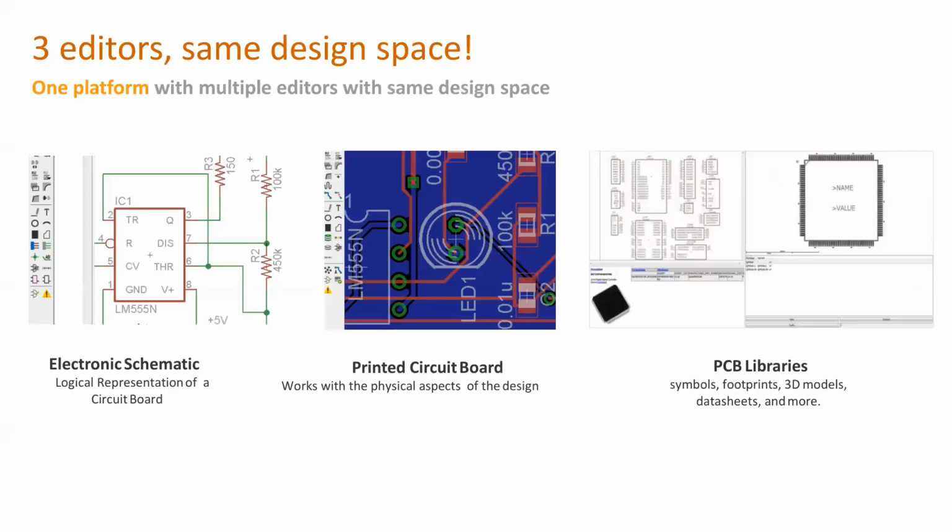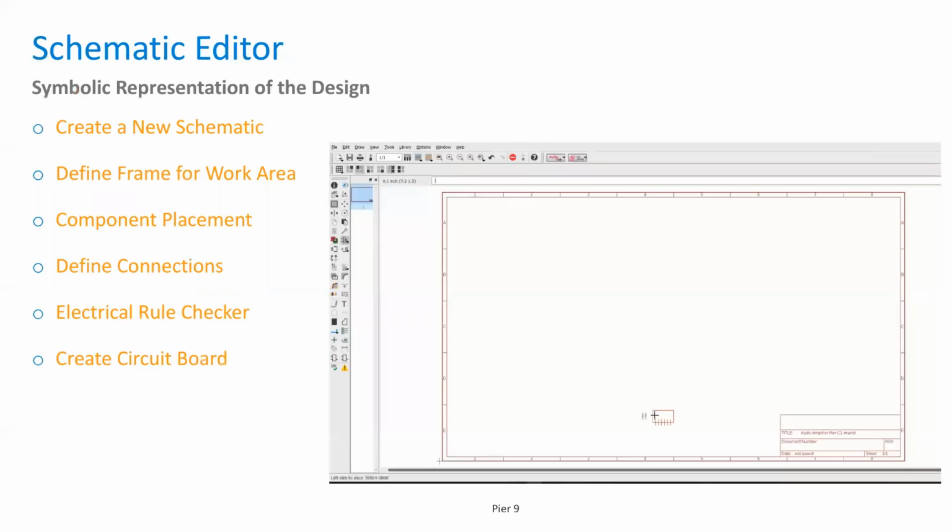And last but not least, and we're not going to be talking about this today, is the PCB library editor, which has its own portion of editors within itself as well. We're mainly going to be working on the schematic as well as the circuit board editor, and we'll also be doing some manufacturing files.